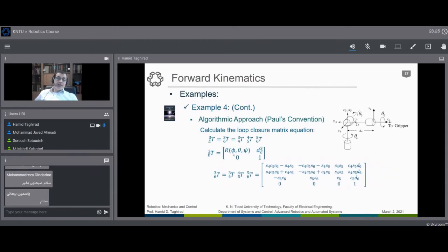We have a rotation matrix or orientation considered by 3 angles. This could be any type of angle that you wish. We prefer to use the screw axis, the axis of rotation, and the angle of rotation about this axis. And we have an offset D, as we have D6 here, which gives you the length of the manipulator here.